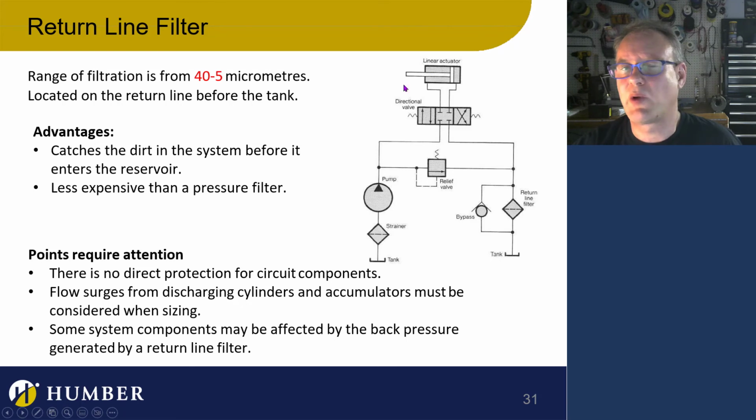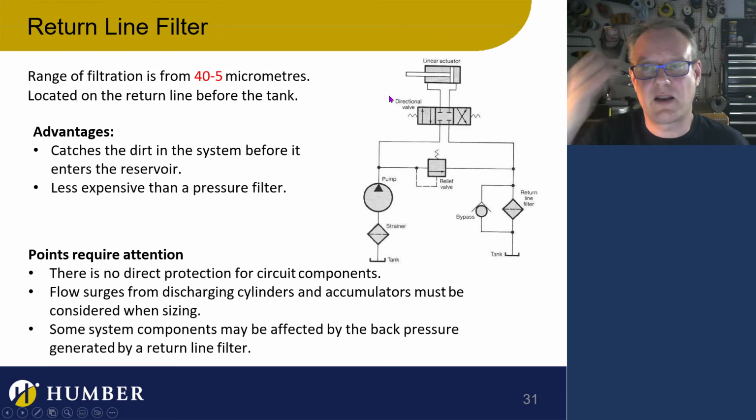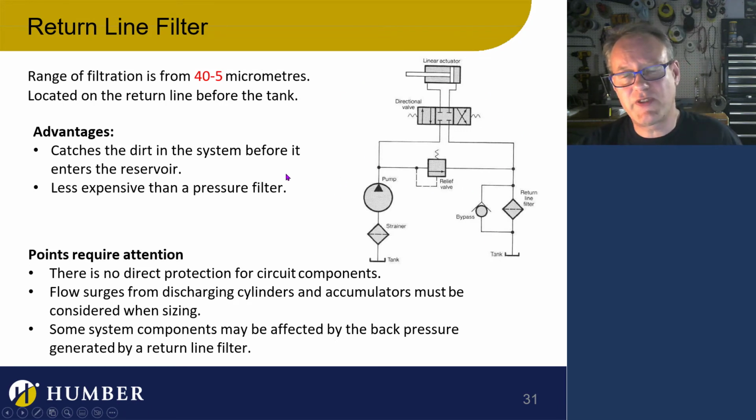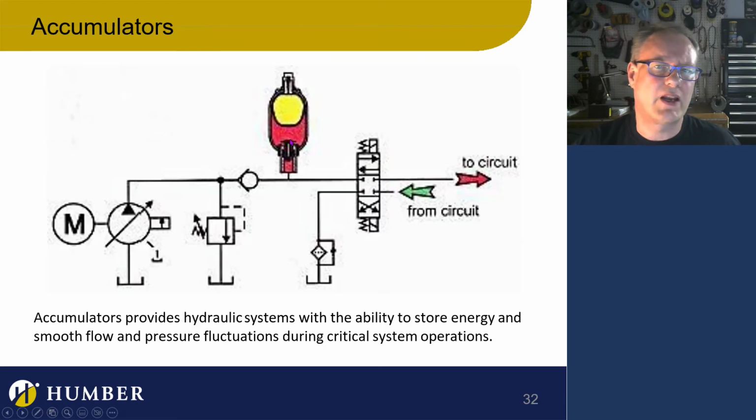That's not the point of this lecture, but it is the understanding that the pressure that's going to be dropping across here is going to be coming from the actuator, from the actual efficiency of the actuator. So when you're putting these filters in, every component you put in is going to steal pressure from the system. So you want to overrate everything. It's important to do that.